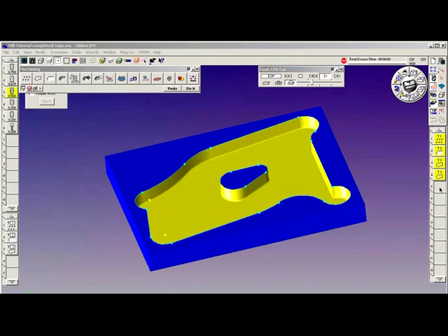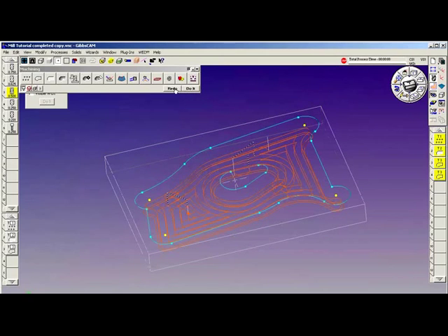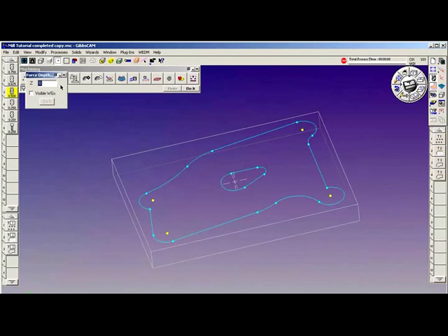Next, if you notice in version 9, the do it and redo buttons are both active. So it's no longer necessary that you deselect the operations on the right. If you're going to make a new one, you just click on the do it button. So you could leave these selected, make a new series of ops, hit the do it command, and not worry about overwriting these. If you hit redo it, then you have an issue. You'll overwrite the commands. I'm going to deselect simply because I'm in the habit of deselecting, and dump my processes. Got to get rid of them, make some new ones.